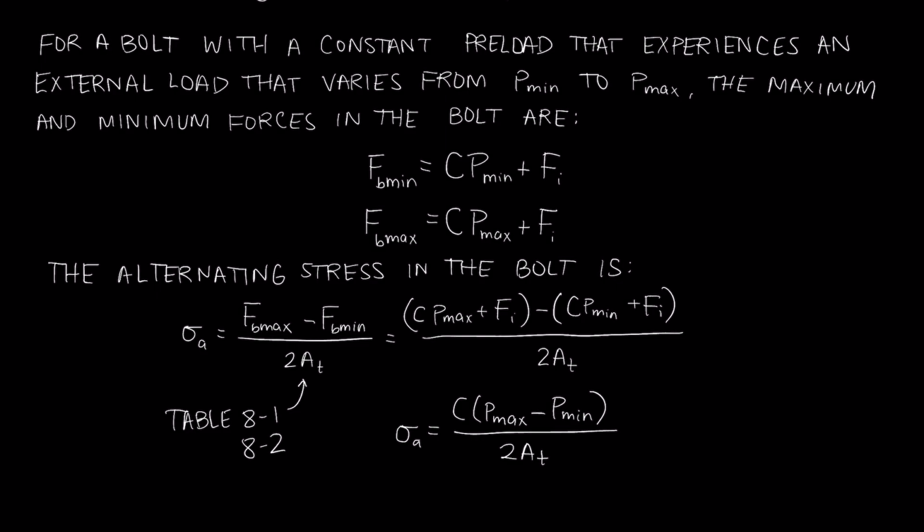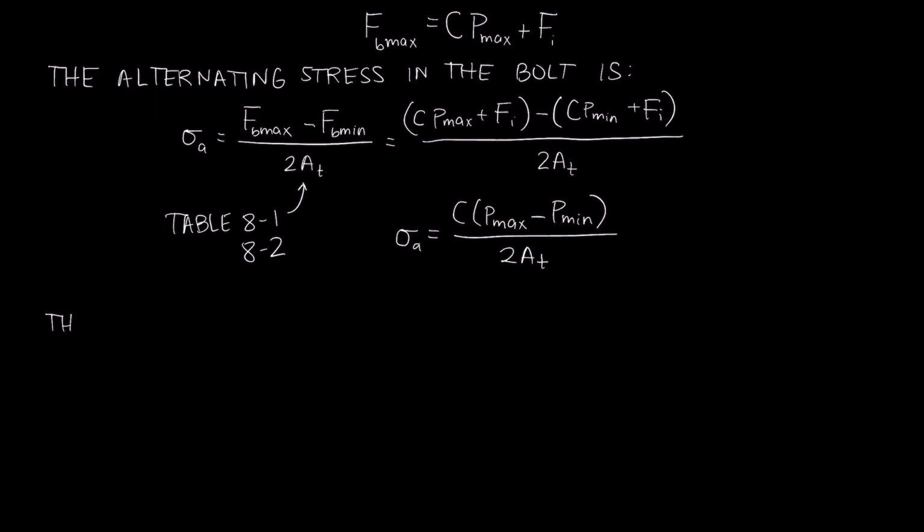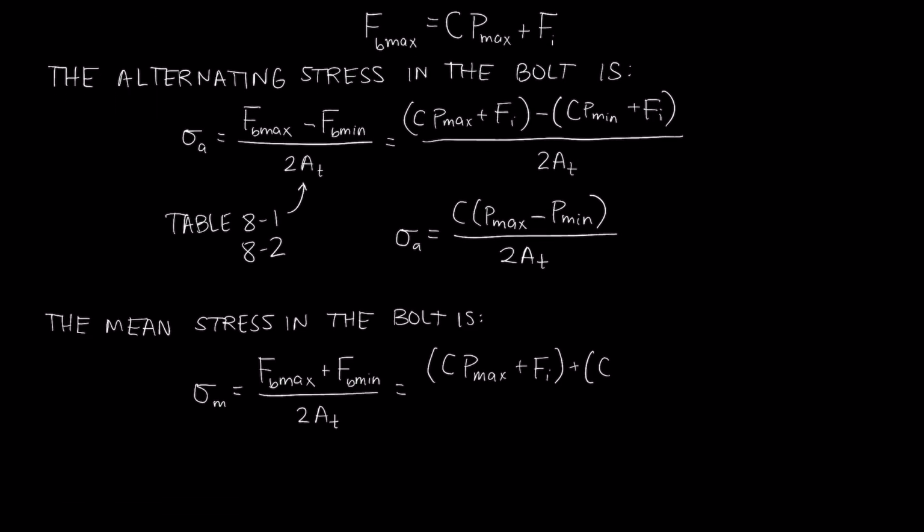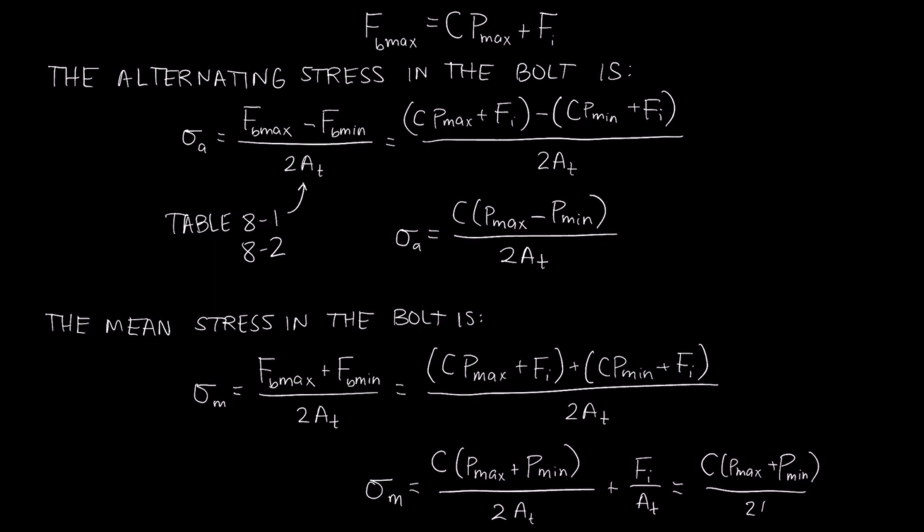Now let's do the same thing for our mean stress or our mid-range stress. Okay, something important to note before we move on here too is that because we're using this tensile stress area in all of these equations to calculate the stress in the bolt, that means that we're looking at the stress in the threaded portion of the bolt. And normally that is a very reasonable thing to do.